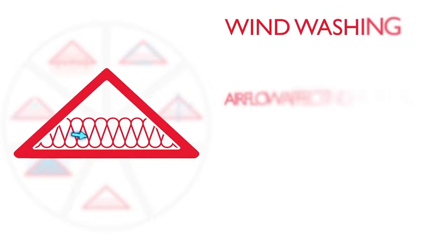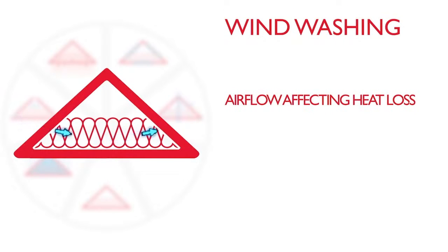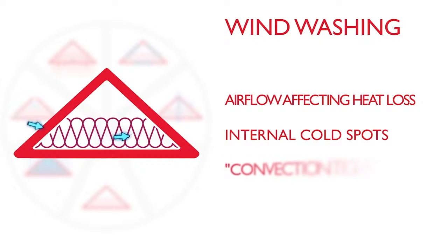Insulation and wind washing. Wind washing describes the process of weather-driven airflow inducing additional heat transfer through the insulation layers. In extreme cases, this airflow can also affect the dew points by moving colder air further inwards. Although this issue is more prevalent with permeable fibrous insulation, it's worth bearing in mind that simply friction fitting rigid vapour and airtight insulation boards between structural members may not be convection tight.